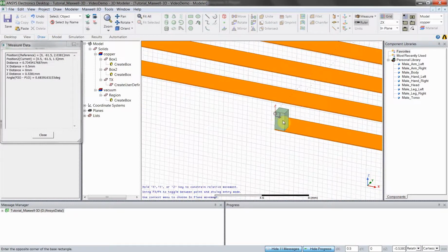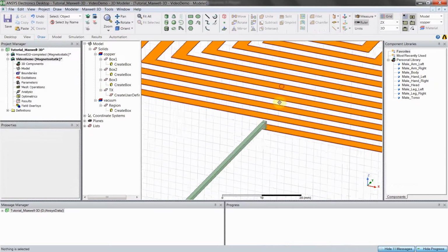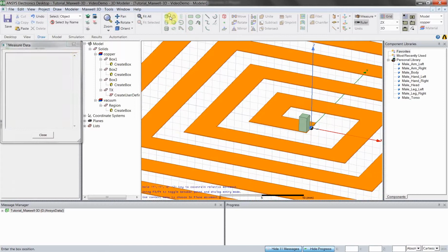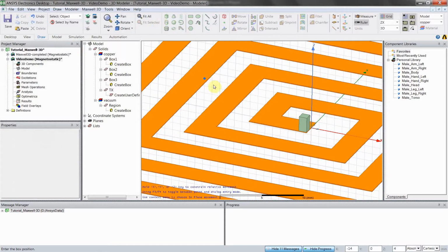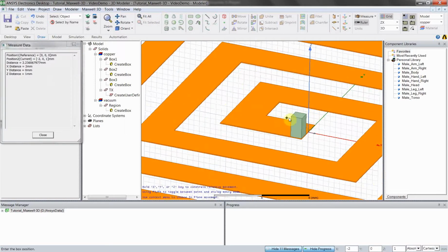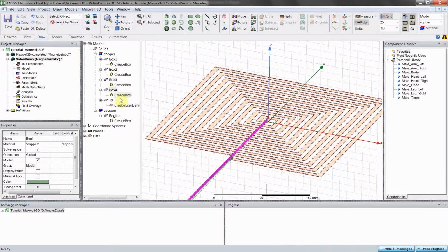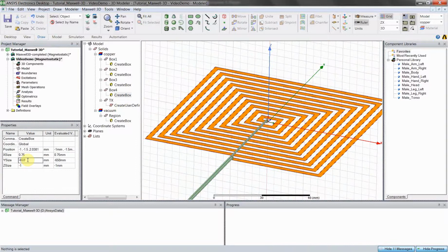So yeah, just making the little box here. Right now we don't know the exact distance to the edge of that region, so let's just overcompensate and say it's 600 millimeters away. So have that lead. And for this lead, we're going to do the same thing, but we also want to make sure that our leads are not touching. So let's make this slightly smaller than 1 millimeter, like 0.75. And this will also be negative 650 just to be safe. Let's say negative 700, why not?